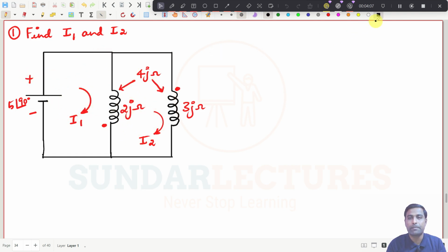So you see here, this is I1. What is the current here? It is I1, and this is now I2. If this is the direction, where one current is coming in and the other is going away, then obviously it will be I1 minus I2. These kinds of basics I am not doing in detail, because you know, you apply KCL here, you make it as X, and this current will obviously be I1 minus I2. You know these kinds of things.